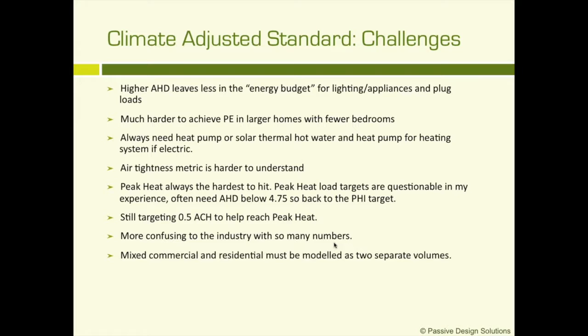Because people can wrap their head around air changes per hour, but CFM per square foot of building envelope is more difficult to get your hands around. The peak heat load has actually been the hardest for us to hit, and from our experience, I'm still really questioning those targets set by PHIUS.